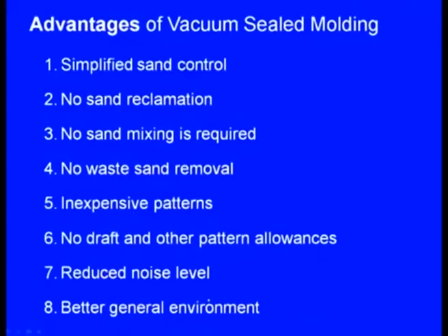So, that is how there will be minimum machining. Next one, reduced noise level. In the case of green sand moulding, noise will be generated, as sand will be mulled in a sand muller. That causes noise, and there will be a sand conditioning plant, because of which noise will be generated. Here no noise is generated. In fact, there will be very little noise.